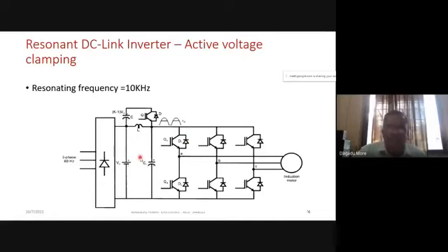Whenever this capacitor voltage increases to 1.5 times VD, if you mark the upper point here, this voltage will be 1.5 VD, because this is VD and this is 1/2 VD. And whenever the capacitor voltage is greater than 1.5 VD, what will happen to the diode?